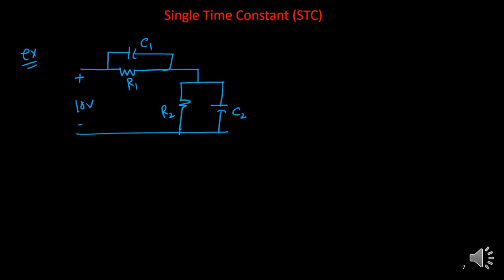So now how to visualize these things, and why is it so? It will always give you a first order circuit, okay? So you can see that the total voltage, this is VI equals 10 volt. This voltage is your VC1, this voltage is VC2. One thing you can understand is that total voltage VI equals VC1 plus VC2. Now, how to find the current and voltage, all the things.